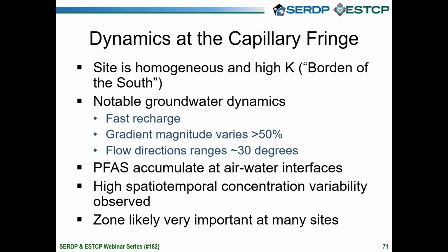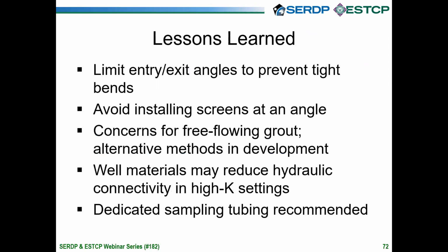I didn't mention it previously, but we do have additional monitoring infrastructure that is focused immediately near the water table, and we observe very high spatial and temporal concentration variability over the duration of a year. And the point here is that this zone immediately near the water table is likely very important for many sites, particularly with respect to PFAS transport and mass discharge. And so a general recommendation is that this zone should be given special consideration when we're designing monitoring programs.